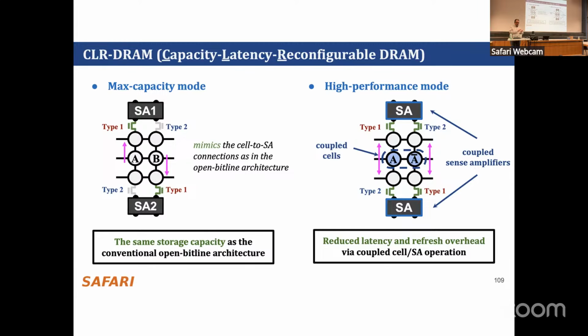For example, in flash memory, we have a single level cell, where you can store only 1 bit in each cell, and that provides a very good speedup, like high performance access. But you can also store multiple bits, for example 2 bits or 3 bits in your NAND flash cell, and that provides better capacity but lower performance.